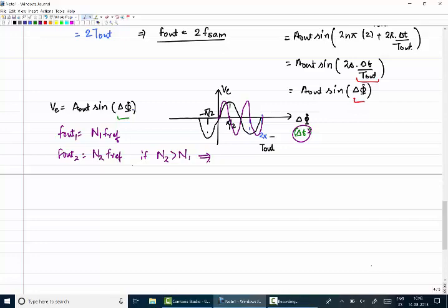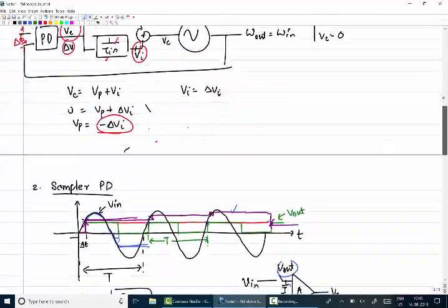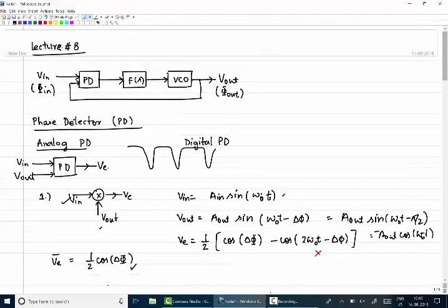Okay, and we have not yet looked at clock multipliers, which means that in a clock multiplier you have a divide by n on frequency in the feedback loop, such that the two signals which come at the phase error detector, in locked state, should be of the same frequency.